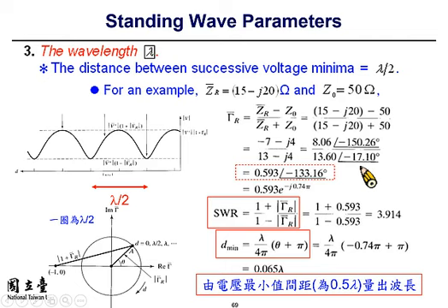All right, so the rest of the slide says that you can calculate those three critical parameters, I mean the standing wave ratio, the distance of the first voltage minimum, and the wavelength, using known transmission line properties. So here's an example. Assuming that the characteristic impedance of the line is 15 ohm, which is a very generous assumption, and the load of the termination is 15 minus 20j. As you can see, it's a complex number. Now it's a more general case.